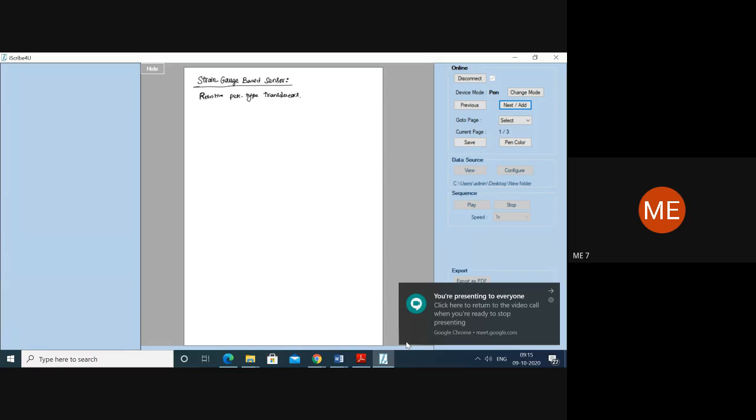Now if you have understood the basic concept, we have made it as the 4 resistors of the Wheatstone bridge network. This is one method by which you can have your strain gauges. So one of the resistances is going to change. Now you know that in the case of strain gauges, the resistance of the strain gauges changes in accordance with the load which you apply. The load may be a force or something else.